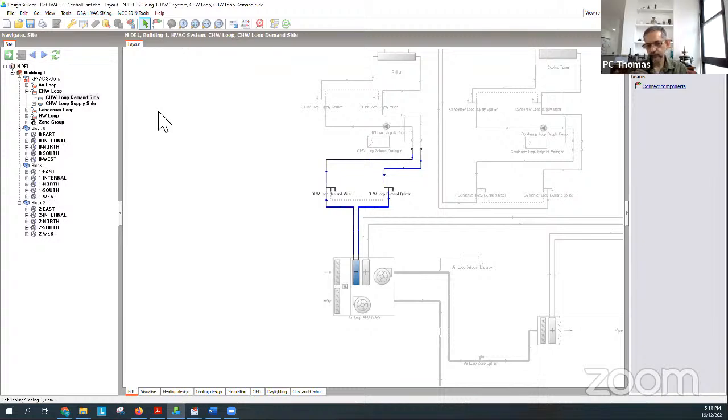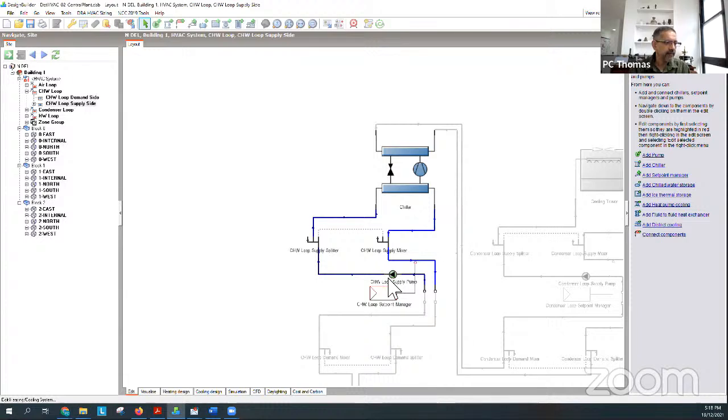So when you say zone group, it's got the same kind of zone type for all the zone groups which are being supplied by the AHU. So this one AHU coil is demanding chilled water for the whole building, right? And this chiller, this pump, and this setpoint manager or controller, is supplying chilled water to the building. Okay.